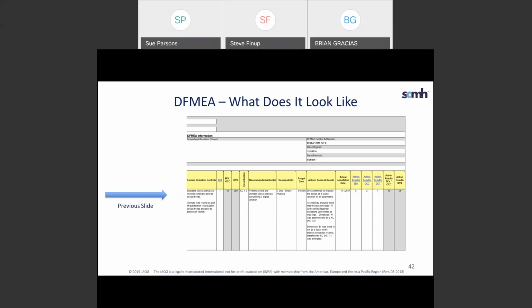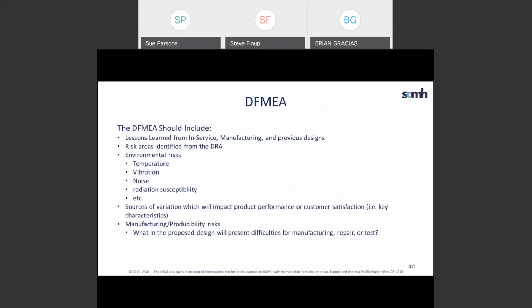Failure modes caused by a lack of control, in parentheses, manufacturing, should be analyzed in the DFMEA? That's a question. Well, that should be part of your PFMEA exercise, looking at the control within your manufacturing process. So the PFMEA would be looking at process risk, manufacturing process risk, and the ability to control your variables.